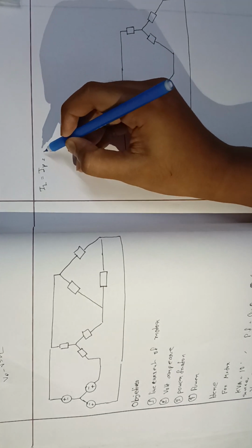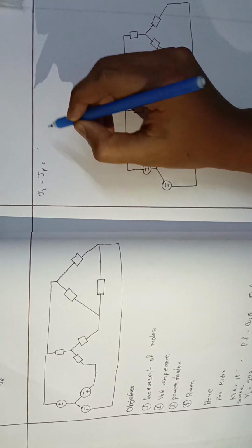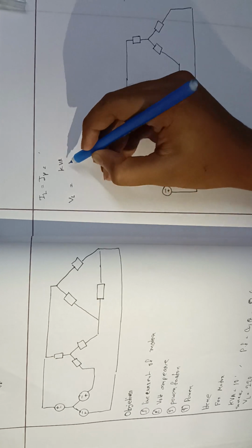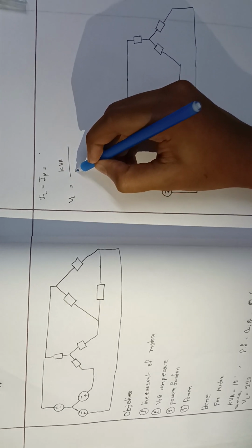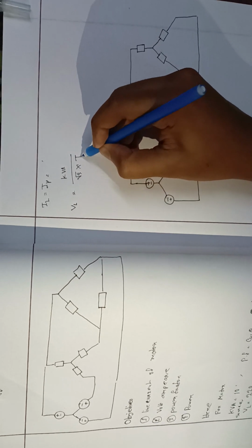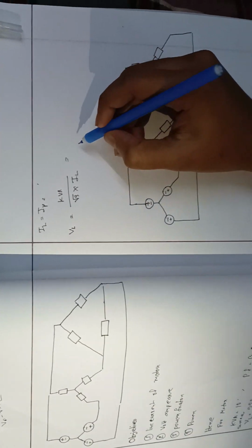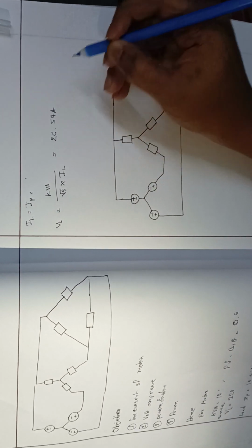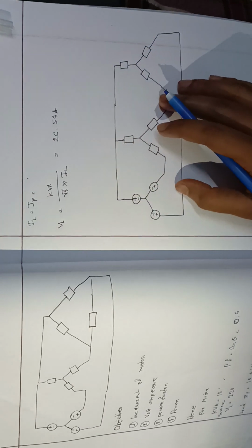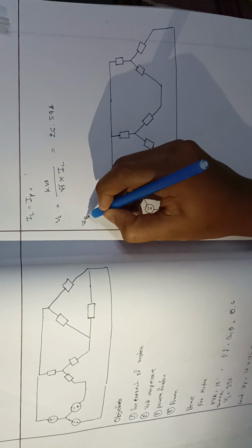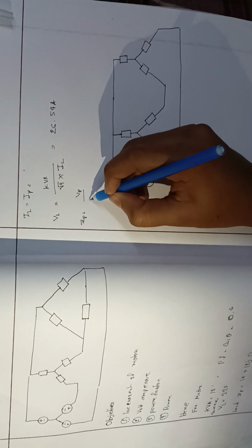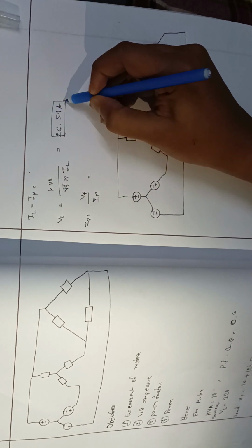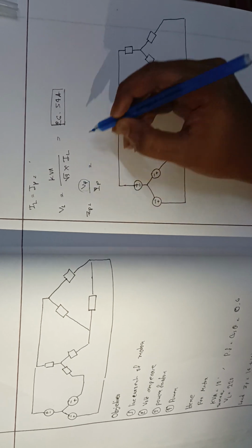So we can easily measure the line current as kVA over root 3 VL. Here the motor line current or phase current is 26.54 ampere. As for the equivalent impedance, we know that the phase impedance is equal to phase voltage divided by phase current. We have the phase current from the previous equation, but we don't have the phase voltage.